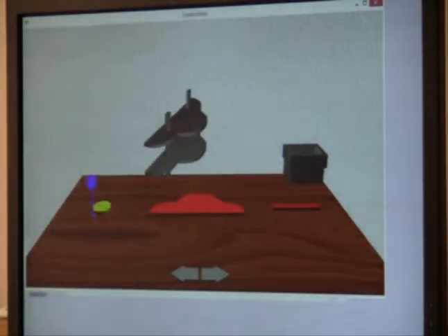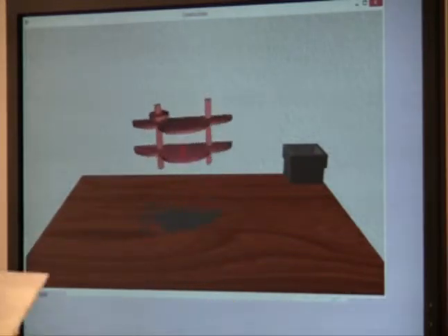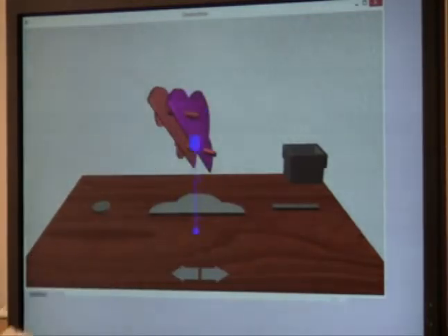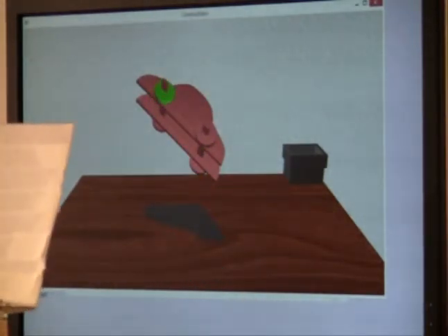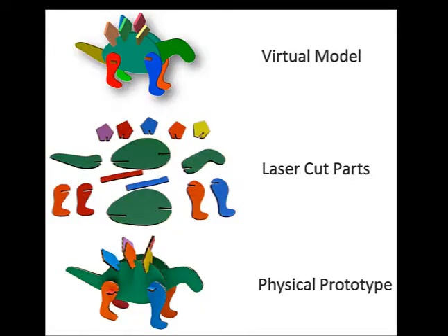During design construction, users only need to approximately define the relative positions of the shapes. Our system automatically infers perpendicularity, parallelism, and alignment constraints between shapes based on their proximity. Proto-TAI automatically creates notch joints between adjoining shapes in the 3D prototype. Individual shapes can thus be easily fabricated in a laser cutter and assembled on the fly to create physical models.